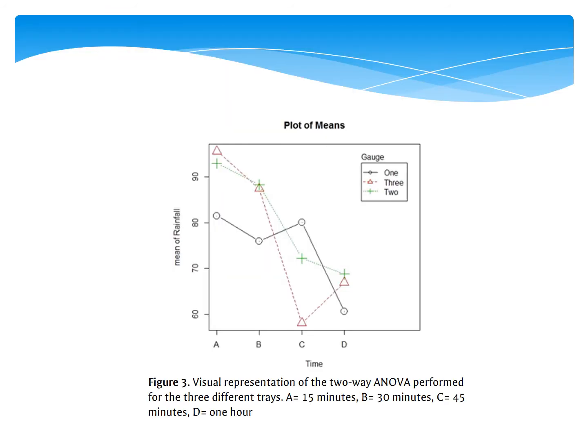From both the raw data and visual representation, it is clear that no significant difference occurs amongst the three trays, hence indicating that rainfall received at each tray was similar. Here, at each time step, it can be seen that different gauges display the maximum rainfall rate. Results from this analysis therefore confirm the suspicions that differences amongst replicates were a result of surface roughness, with increased compaction and smoothness observed in tray C.